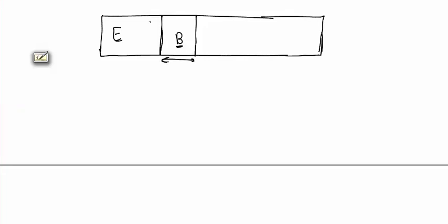If we are injecting majority charge carriers into the base region, then we should ensure that the concentration of electrons in base region, that is n, and concentration of electrons in collector region, as collector is n type region, this will be very large, but as we are injecting electrons into base region, the electron concentration in base region will increase and should be greater than n dash. This we have to ensure.